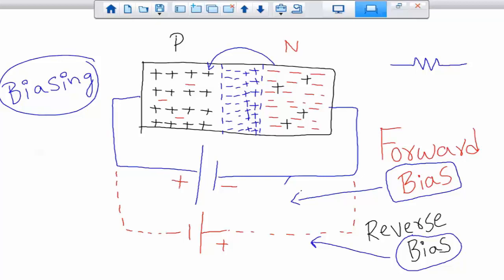But for a p-n junction, you need to exceed the barrier to have a decent current flow, correct? So now can you compare with resistors, capacitors, inductors? Those don't have any minimum voltage requirement. If you apply 1 volt, they work. If you apply 0.5 volts, they work. As long as you have some voltage, they behave the way they're supposed to.